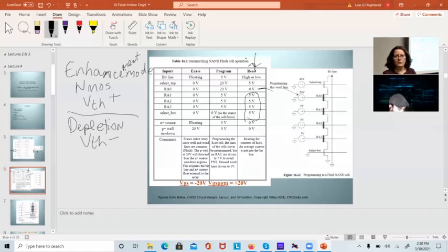When I was at Motorola, for our final stage power amplifier, it was 1 gigahertz, so normal MOSFETs didn't work. First of all, they were made out of gallium arsenide. Second of all, they were MESFETs, not MOSFETs.